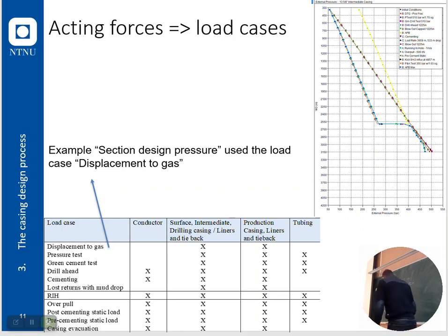Cement goes from liquid phase to solid, like this, and then grains form into it, like this, and it goes from liquid to solid in typically anything from 3 to 6 hours. It depends on your design, your composition, and everything else that you have.